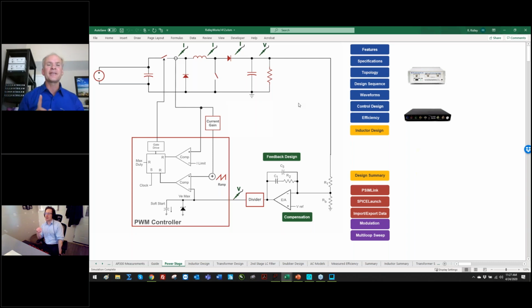There is a catch on using this method. You can't sweep an unstable circuit. Simplis has a function of getting the small signal from the large signal, but you can't do it for an unstable circuit. If you're on the bench, you can't sweep an unstable circuit either. You have to stabilize it first. That usually means pushing down the gain, then sweeping it.